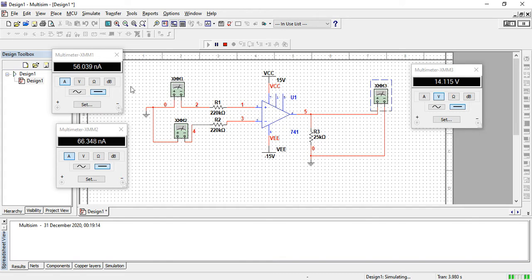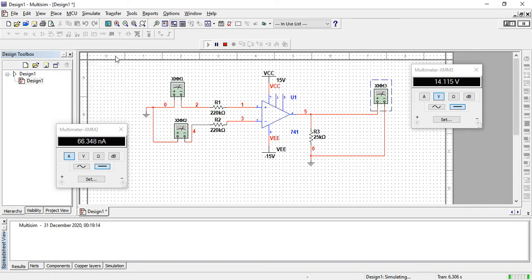And still when there's nothing, no signal, no millivolt signal connected to your terminals, you are still getting an output voltage, and here you can take these two as input offset currents, right? And the difference would be your value, right? Now let's move toward the final concept of offset voltages.